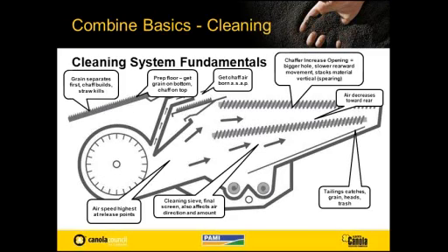The fan itself usually delivers an air blast that's quite strong along the bottom of the fan housing and again at the cutoff points. So what you get is one blast of air going underneath the cleaning sieve, and if the cleaning sieve is very closed, it will travel underneath the sieve and either exit up through the tailing section or will just basically stall. But typically you'll find it going up through the tailing section.